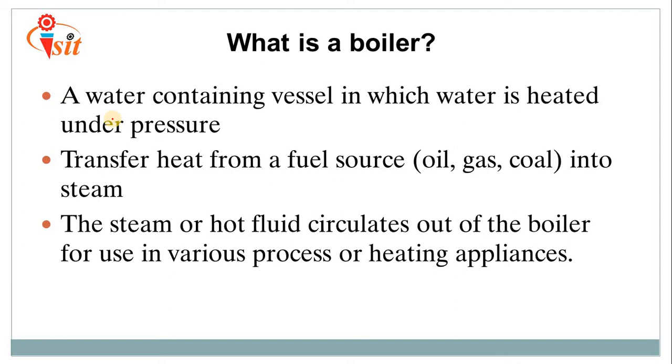Okay, so generally various kinds of fuels are used. Oil fired boilers are there, gas fired boilers, coal fired boilers, and wood fired boilers. Mostly in our area, in the textile industry, small capacity boilers are used, where we want steam for sizing as well as for the processing unit. We want a small boiler which works between 1 bar and around 15 bar. At that time we can prefer wood as a fuel.